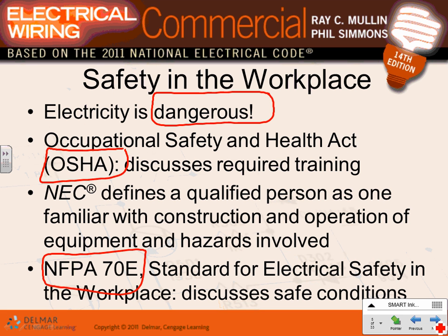Meaning that big ball of fire, how far is that big ball of fire from the panel going to go? Typically 5 feet, unless you do the calculation. So if you put yourself 10 feet away, you are completely out of the arc. That big ball of fire is going to chase you.